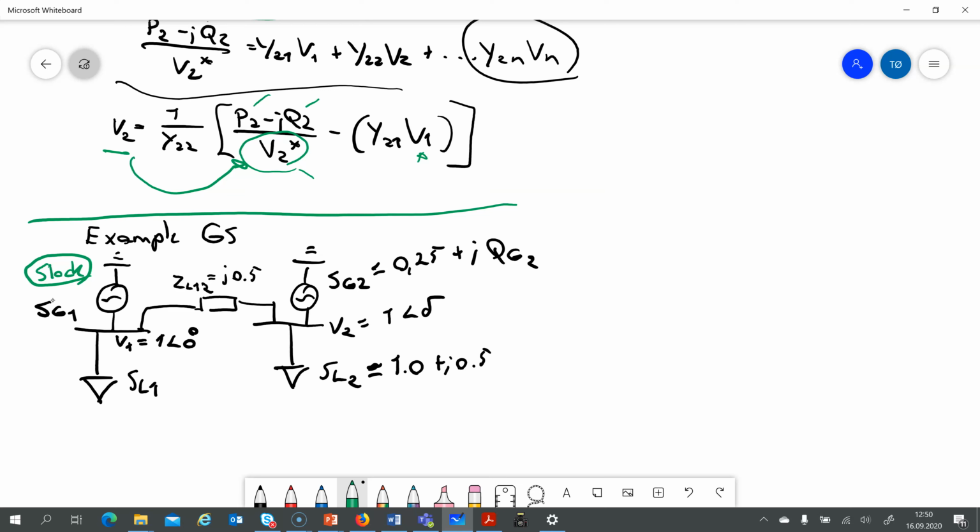So we have a couple of unknowns we need to find. We have these two buses, and on this bus here we know there's a load connected. That is defined in per unit, but we don't know the angle in that bus, and we don't know how much reactive power is necessary from the generator. So these are things we have to calculate.